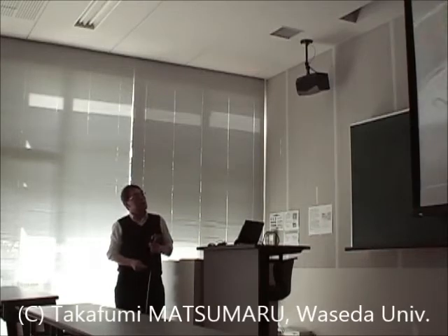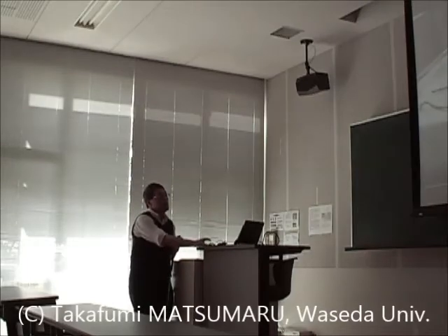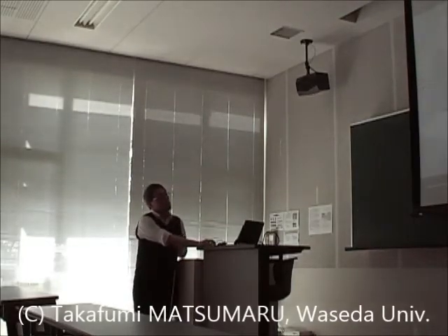I also briefly tried putting these on the outer wings of my latest scratch-built RC plane, and I could definitely tell a difference. It just felt safer and more controllable at low speeds. The inner wing would easily stall, but the outer wing would maintain control. It's pretty interesting how you can actually hear the wake of the wing. At high speeds and low angles of attack, the air is smooth, but at low speeds and high angles of attack, the wing's turbulent wake is hitting the tail surfaces and the camera.